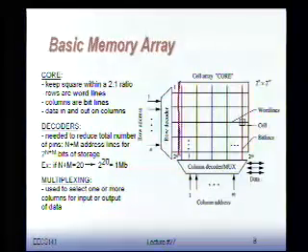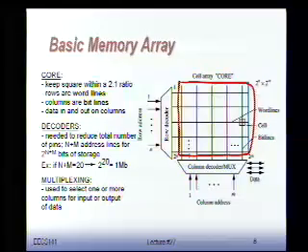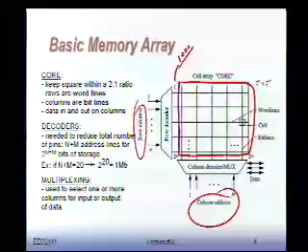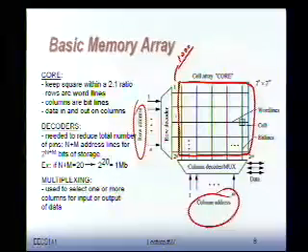So you have the memory core, which is m times n. And we have the row address and the column address coming in. Now, if I had, let's say, a 1000 by 1000 memory, just an example, that's a million bit memory, it means I have 1000 rows in this direction, 1000 columns in the other direction, right? Now, the address I could do in pure binary format. It's 1 when you want to address it, 0 when you don't address a row. But that's a pain in the neck too, because 1000 for the row address, 1000 for the column, that's 2000 bits. You can imagine that it would require a lot of pins on your package.